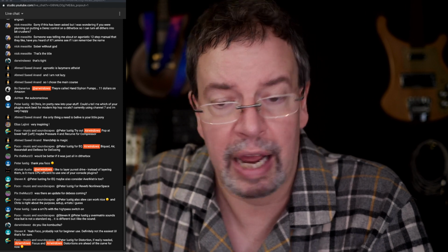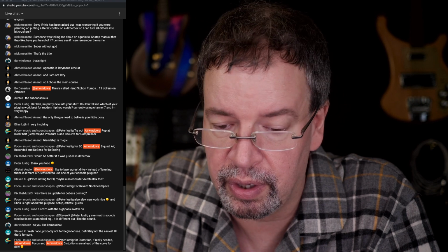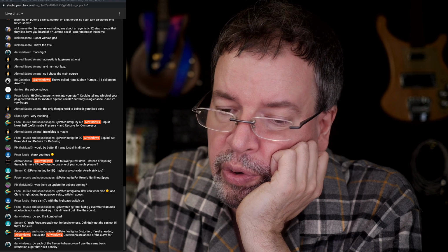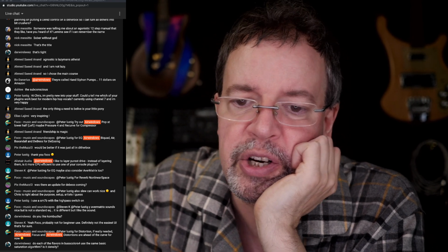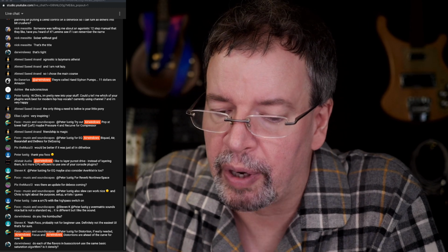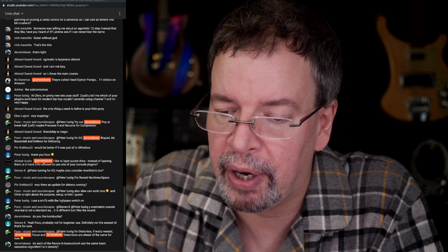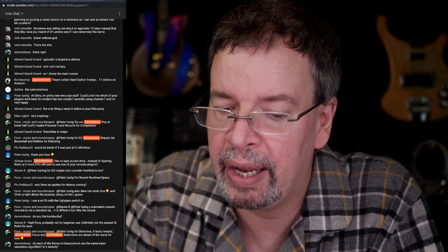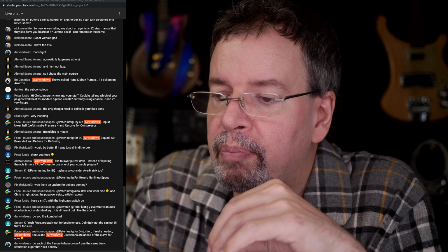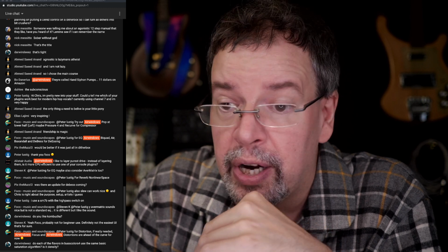If you like this type of sound, you can take your cheaper microphone, because cheaper microphones are noisier, but they also don't saturate as nicely or at all. Little measurement microphones, little Electret microphones, they might saturate, but back off a little bit and they're going to act like measurement microphones. They're noisier, but they're tiny, and probably have a higher dynamic range than large diaphragm microphones.